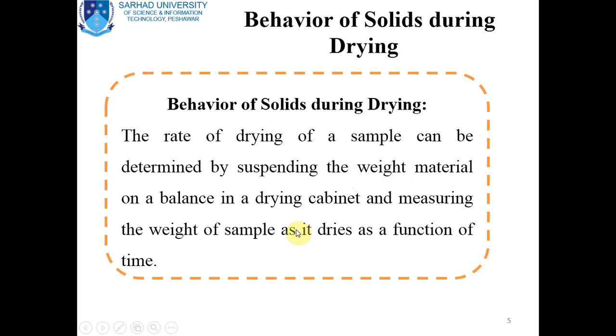We have to measure the initial weight of the sample, which is a combination of the solid material as well as the solvent system, and then we have to take the sample again and note the weight when it dries as well as the time at which it dries.